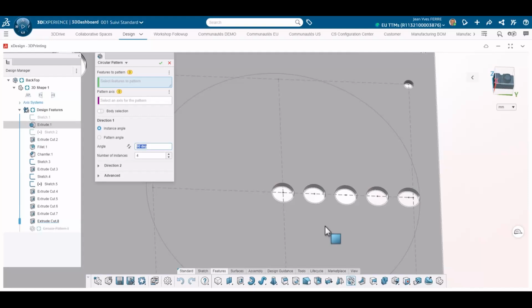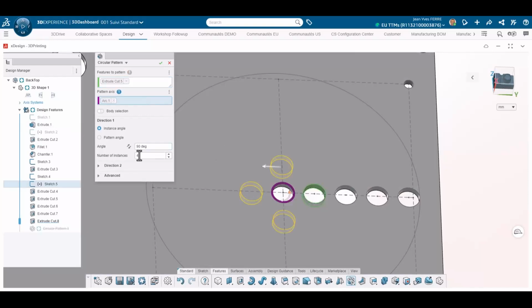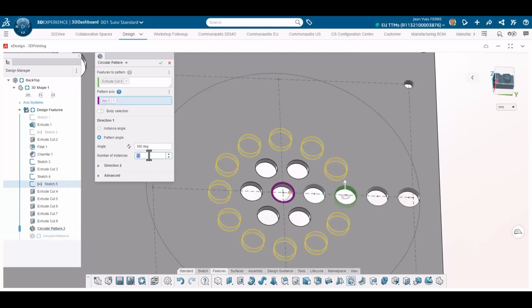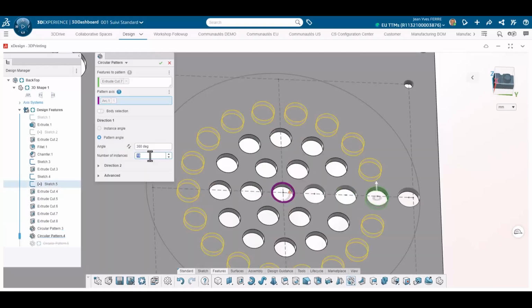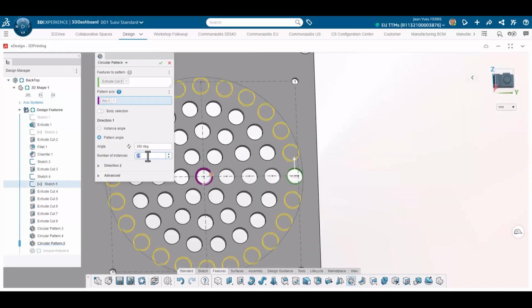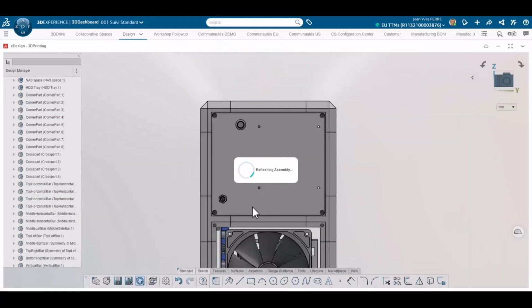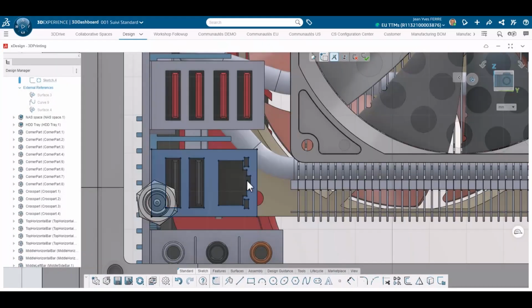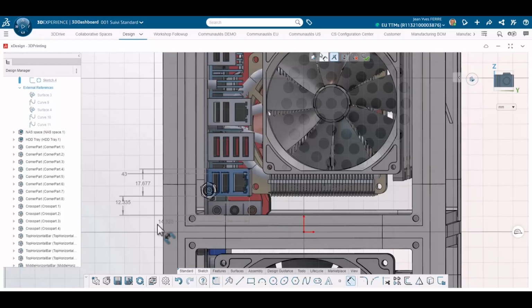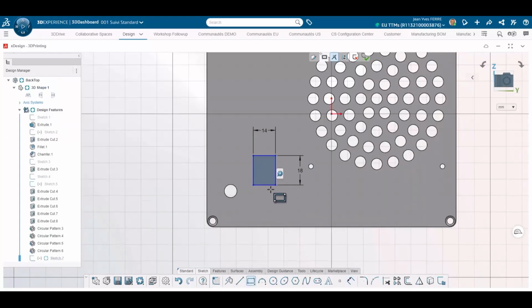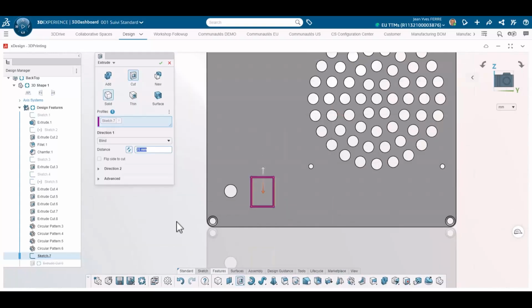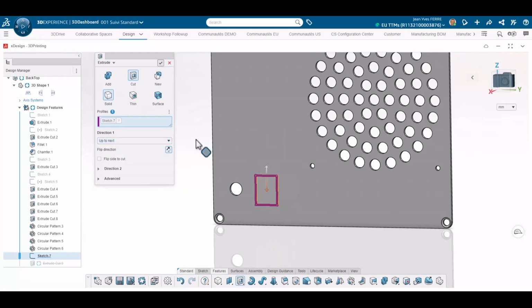Once the initial setup is complete, I create a pattern, experimenting with different values for each repetition. After some testing, I settle on adding 6 additional holes per repetition, using the central hole as the reference for the circular pattern. The result is exactly what I envisioned. Next, I address the network plug. Using measurements from the motherboard, I create a rectangular cutout to accommodate the plug. You might be wondering why I chose this particular network port over the other one on the motherboard. Honestly, I should have wondered the same.